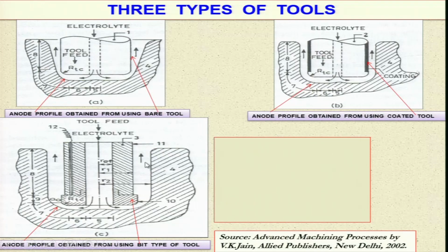So you can clearly see here such a nice control of the inter-electrode gap, and a fully straight-sided machined component is obtained, and this is highly recommended. It can also be used in the case of the ECMM process, where you have very small micro tools, and you can have this bit there and attempt to machine different kinds of components in the ECMM process also.